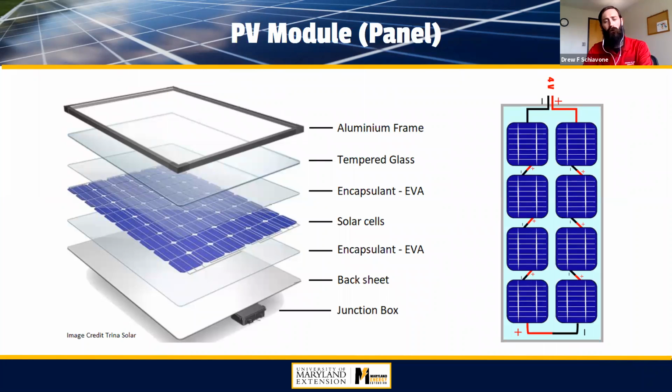Now, what happens with this at the manufacturing stage, they create that series of PV cells. They laminate it on a backing material. They seal it with weatherproof plastic coating, and they put a glass cover on the top. And typically you'll have an aluminum frame around the edges of it. You could use other materials as well. Aluminum's pretty affordable and most common. You could use steel or other things under extreme environments, but for most of our applications, you'll see aluminum framing. That's the basic fabrication process of it.